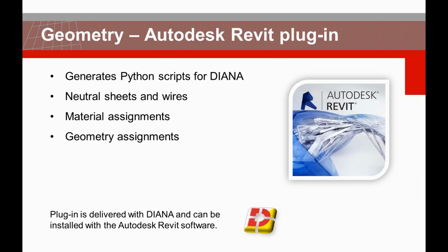And when you have your structure, when you have your project, you can use this plugin, then the program automatically transfers all the geometry information through a Python script ready to be imported in DIANA. So that way you can again transfer your shapes, your material, your geometry, sectional properties into DIANA for further modeling and analysis. So this is another powerful tool that speeds up your modeling process and links your geometry modeler to the analysis program.